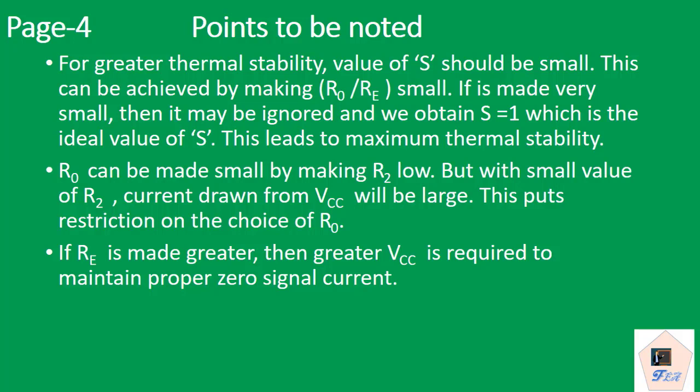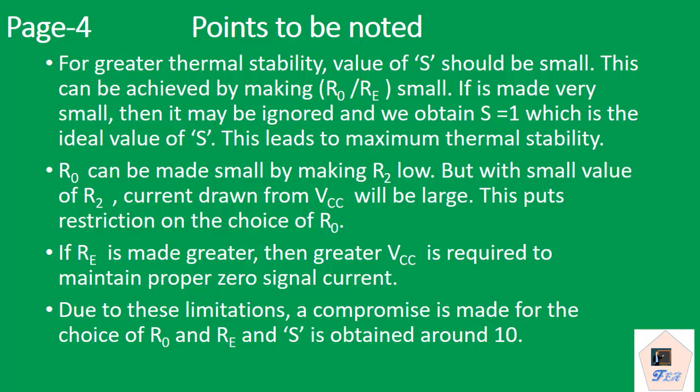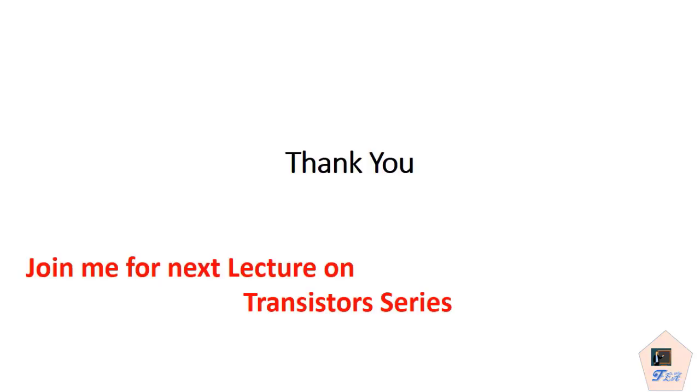However, being an electronics engineer, a designer, we can choose some optimum values of R naught and RE so that we can keep S small, and it may be achieved around 10. That will be a good value of stabilization. So here we end our discussion.